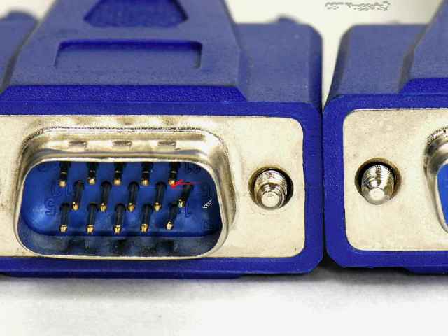Okay, and one thing that I want to tell you about is if you have any of these kinds of cables, whether it's VGA, serial, parallel, whatever, and you have some pin misalignment like that, an easy way to straighten that out is potentially with needle nose pliers. I generally tend to prefer a flat head jeweler's screwdriver, and I just exert a little bit of pressure in the opposite direction here to push it back over where it was supposed to go.